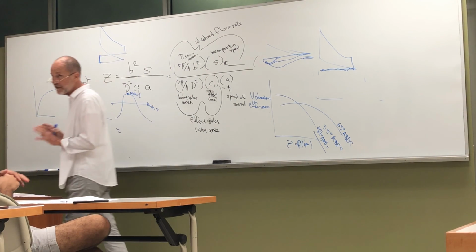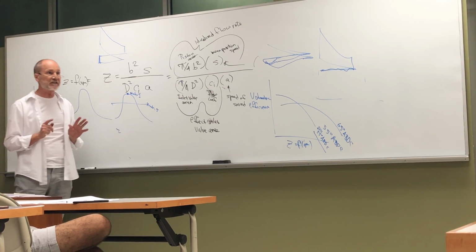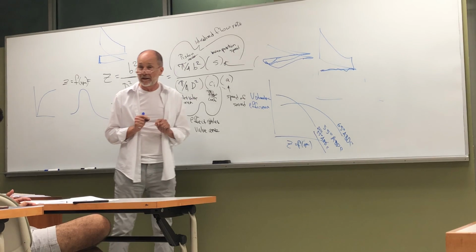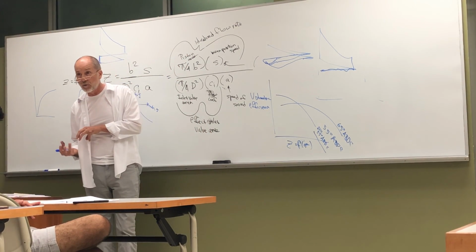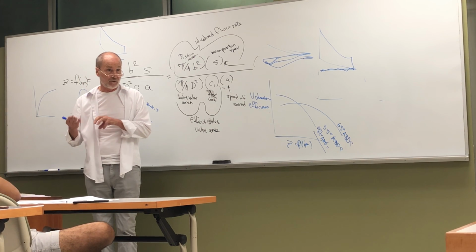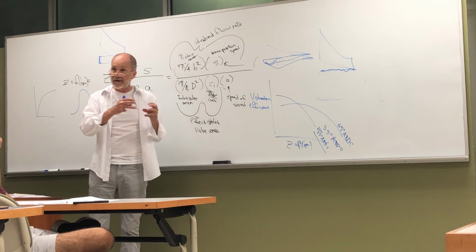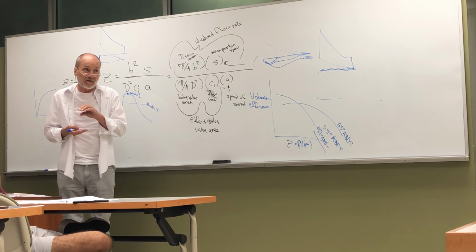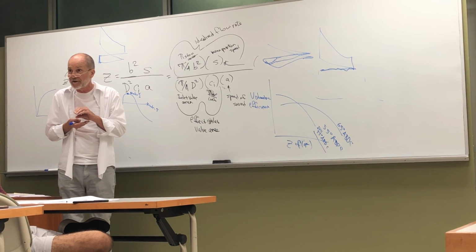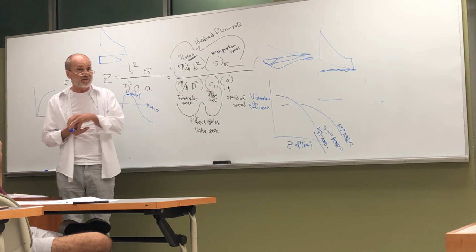The only way we can change the shape of the curve is to close the intake valve at a given time and make use of the momentum of the gases coming toward the intake valve when you hit bottom dead center. You still have momentum in those gases. If you leave the intake valve open, remember the piston's not going to rise rapidly after bottom dead center. We can continue to fill the cylinder.